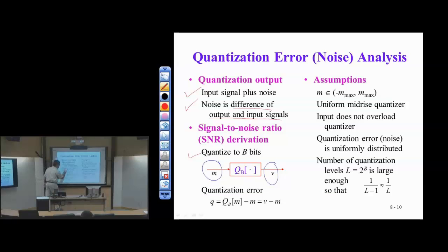Whenever you have a signal-to-noise ratio, there's an implicit assumption that the signal and the noise are statistically independent. And in practice, they rarely are. It's just an approximation to get going on derivations. But the correlation between the two will usually reduce your results. Lower your upper bound, raise your lower bound, whatever. And that's one of the reasons that the upper bound isn't reality. The upper bound is beyond reality, right? It's the case where we're assuming statistical independence.